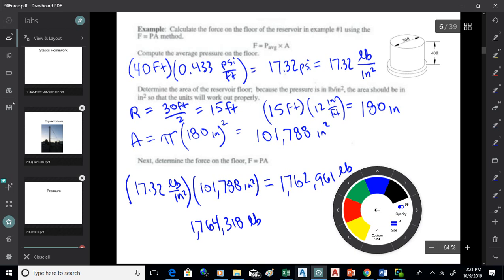The reason is there are some conversion factors here that are rounded. Okay, I use 2 different methods, and they're related to each other, of course. But when you say 1 foot of water is 0.433 psi per foot, it's probably 0.4333333. We've rounded that number. And when we say water is 62.4 pounds per cubic foot, that's rounded, okay? So everything's rounded a little bit. So here's a real good example.